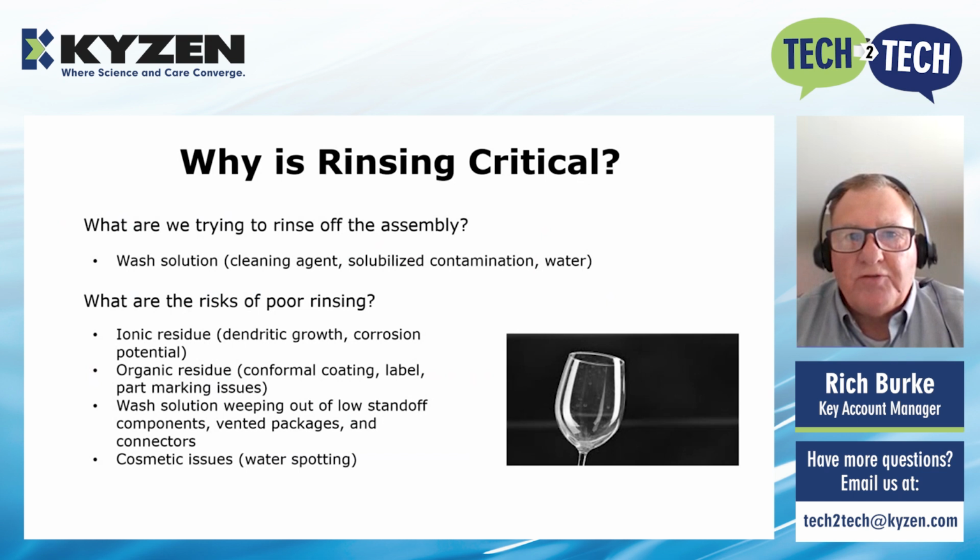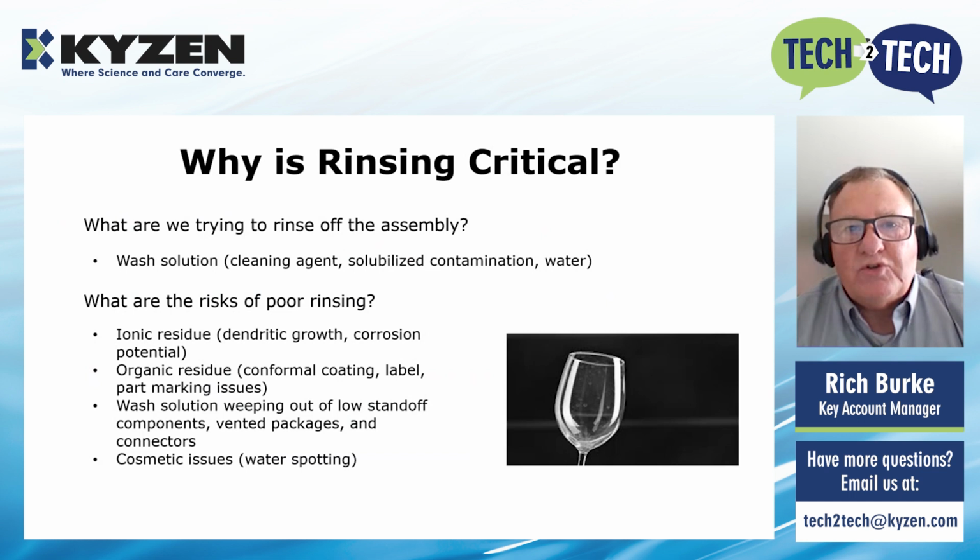Before I jump into those three pillars, let's talk a little bit about why rinsing is critical, and more specifically, what are we trying to rinse off in assembly? We know that we use a wash solution to remove the flux residues in the cleaning process itself. So in essence, that's what we're striving to rinse off in assembly. That wash solution is made up of cleaning agent, obviously, but it's also going to have the solubilized contamination, the rosins, the resins, the flux activators, and so on, and obviously water. So in essence, that's what we're striving to rinse off our electronics assemblies.